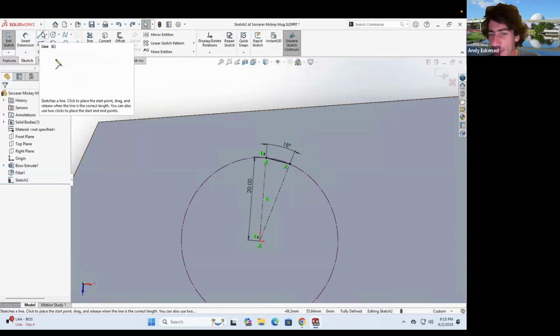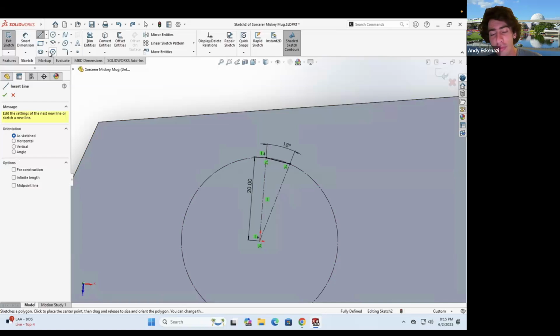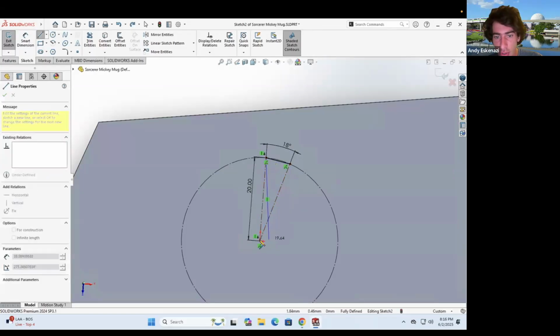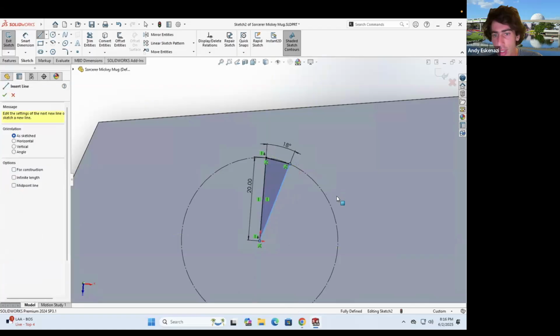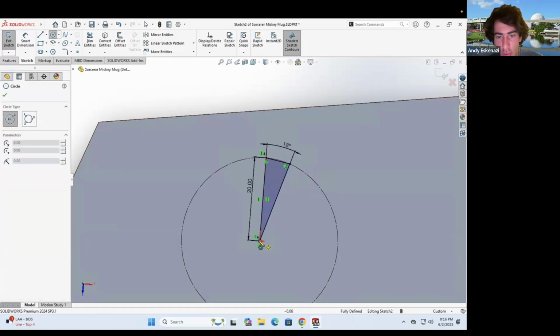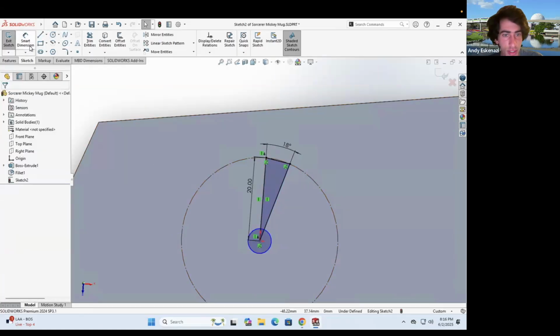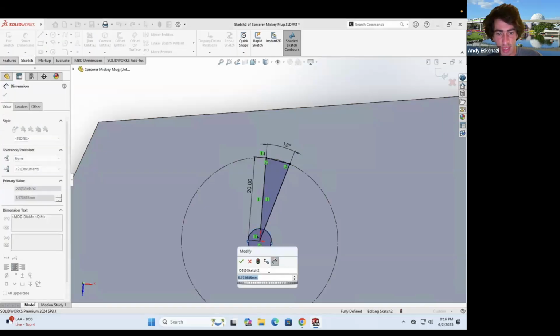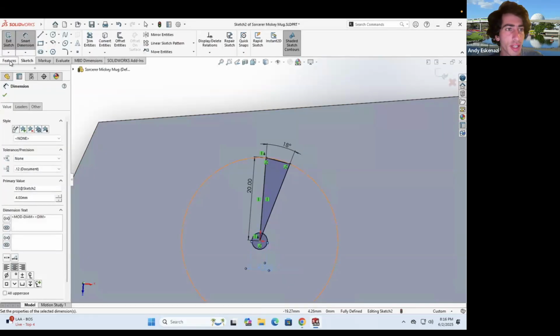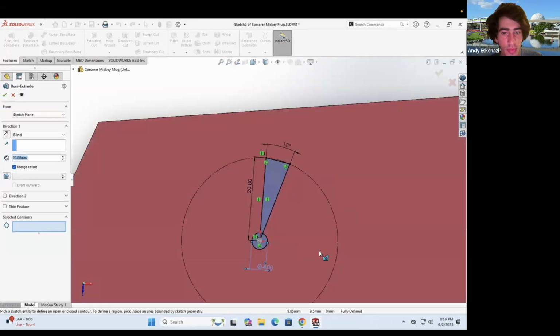I'm not sure why this doesn't want to work, but the good thing about SolidWorks and just debugging in general, just being honest with you, is that there's lots of ways to solve an issue even when it doesn't work. And in a case like this one, which is kind of a bummer, what I would do is just create a little wedge like that. Then I would do a little circle just like this. Let's make it 4, for instance. And I'm going to extrude this.